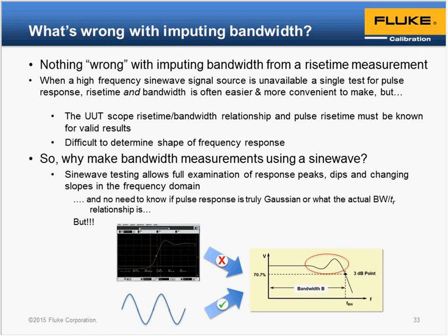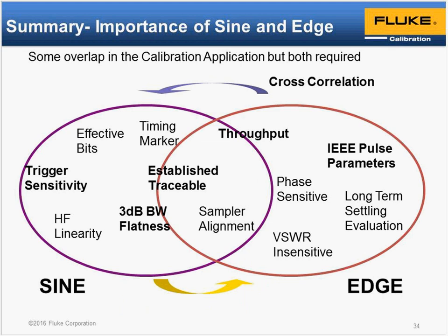Finally, this is the last slide. There are lots of parameters appearing on the slide that we haven't mentioned, and I did mention them up front in the typical list of what's necessary to calibrate an oscilloscope. And the reason is that there are other measurements that very often are not made as a routine recalibration. A performance verification type measurement might be of more interest to the oscilloscope manufacturers at the time of the manufacture or service of that oscilloscope. Such things as you see on here, where we're talking about sampler alignments, effective number of bits, and things like that.